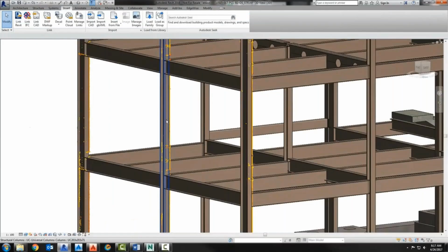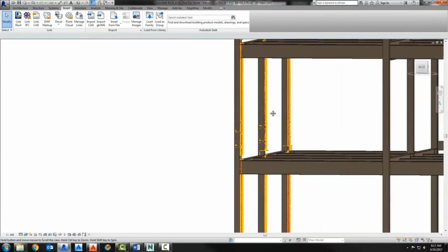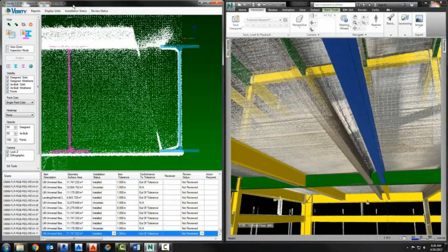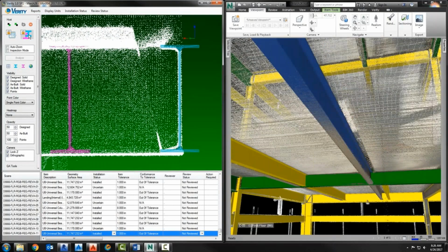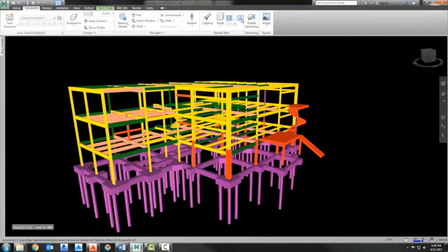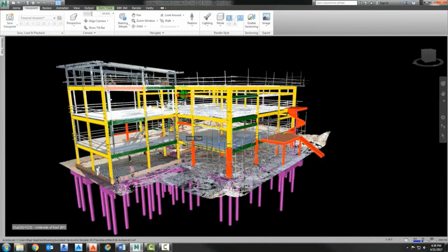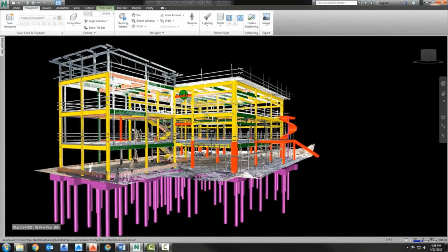Not only that, you can then take your files to Revit. So again, we're doing a building, so I'm concentrating on Revit. And you can actually compare the actual building. Now, this is amazing, where you can see that the point cloud for the beam is on the left. I click the CAD model and it snaps to the correct position now. You will not get this in any other software, as far as I know, because you would have to physically move that in your CAD application, whereas here you just click on it and it will update its location to its as-built properties.